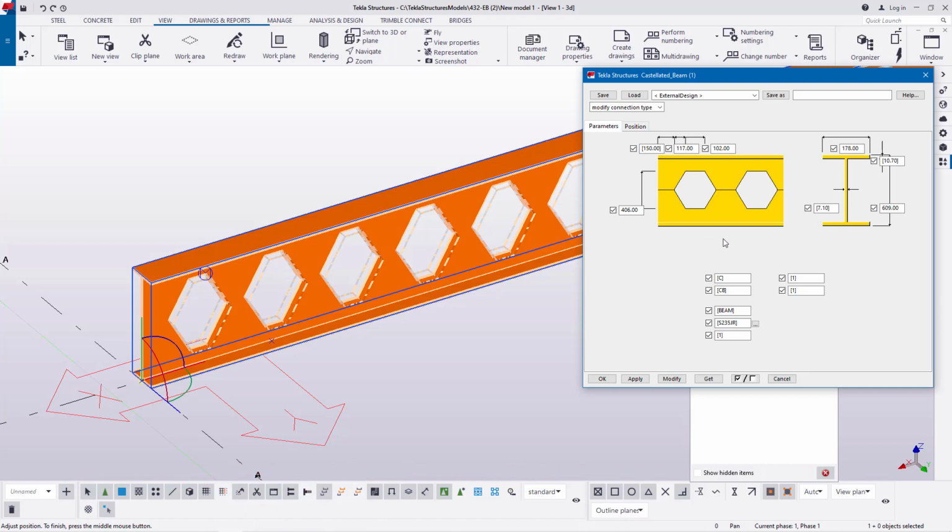Now I'm going to feed in the development and cutting details. I'll start with this point, this end to this end. I'll feed a different measurement. In this case it will be 103, and this distance to this distance I'll feed 89 millimeter, and from this end to this end, you can check on my mouse pointing the points, which defines the far end. This far end to that far end will be 356. So I'll feed 356 right here.